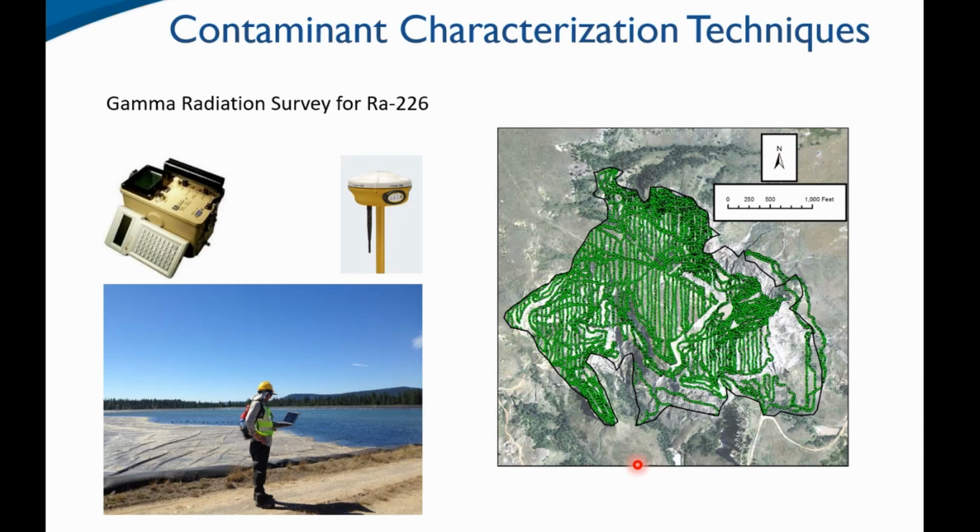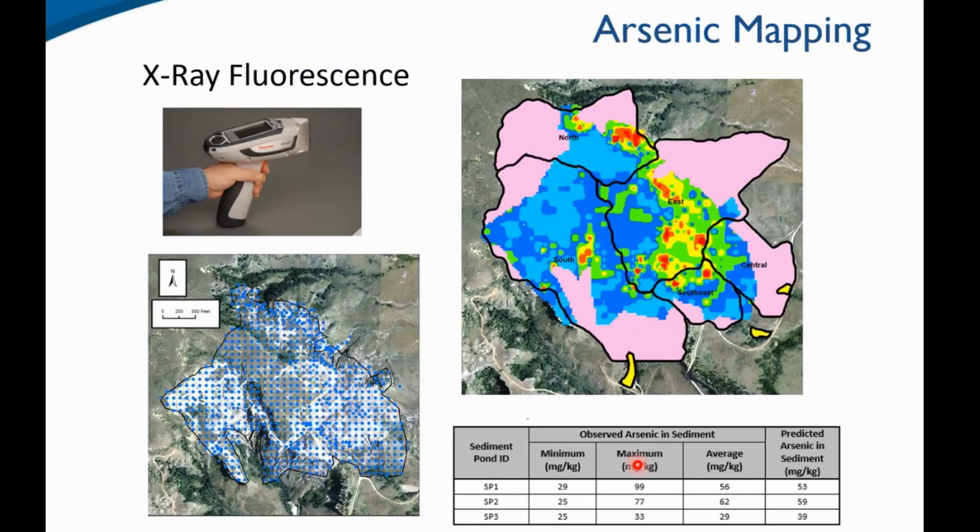The other big development has been that you can put some of those probes on drones, and then you can fly the field. If it's too highly contaminated for you and you don't like it for yourself or for your co-workers, then you can fly the area and collect the information directly in situ and come back home with a nice map of your survey of whichever parameter you have. In this case, it is arsenic, for instance, and it is going to show you the hotspots of the contamination that you have on the ground.